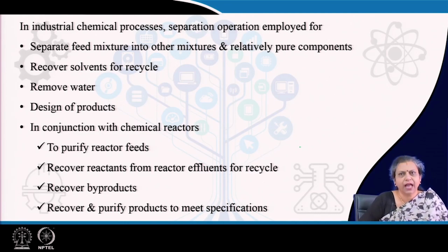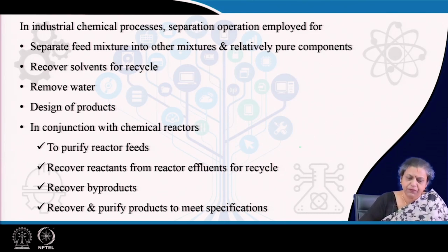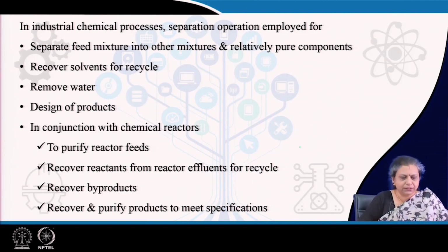Then definitely, as chemical engineers, we very frequently deal with several sorts of reacting systems, and in all these reacting systems, as I have already mentioned, we need to purify the reactor feed before it is fed into the reactor. We need to recover the unreacted reactants from the reactor effluents, and then they need to be recycled. We need to recover the byproducts, and we also need to recover and purify the products which we have obtained from any process in order to meet the specifications.